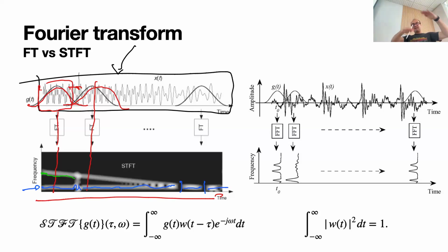So we have a signal that has one constant frequency and one like when a train goes by and you hear this Doppler-like wee, and you can see it in the time domain. It has some high frequency part and then it slows down. And if you do this slicing FFT, you can see that we have one constant and one slowing frequency.